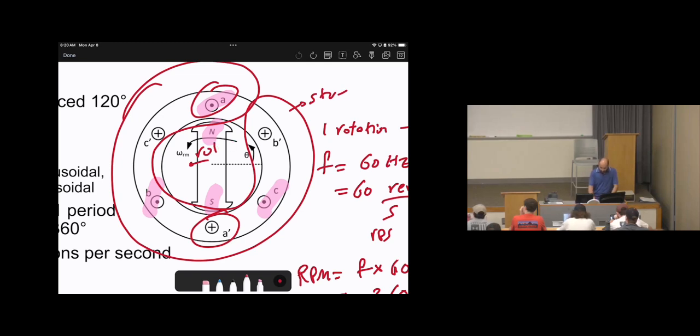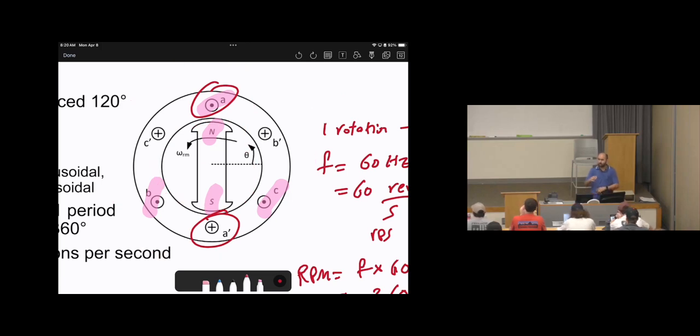So the stator is based on coils, and the electrical energy will be produced in these coils. Coil A, coil B, coil C. Coil means inductance, so there will be a number of turns around the core. This is called inductance, and there is an equivalent circuit for it. The equivalent circuit for the coils will be based on the inductor, and in addition to that, there is an internal resistance. So the stator equivalent circuit will be based on a resistor and inductor. Okay? Does this make sense? Resistor and inductor because there are a number of turns.